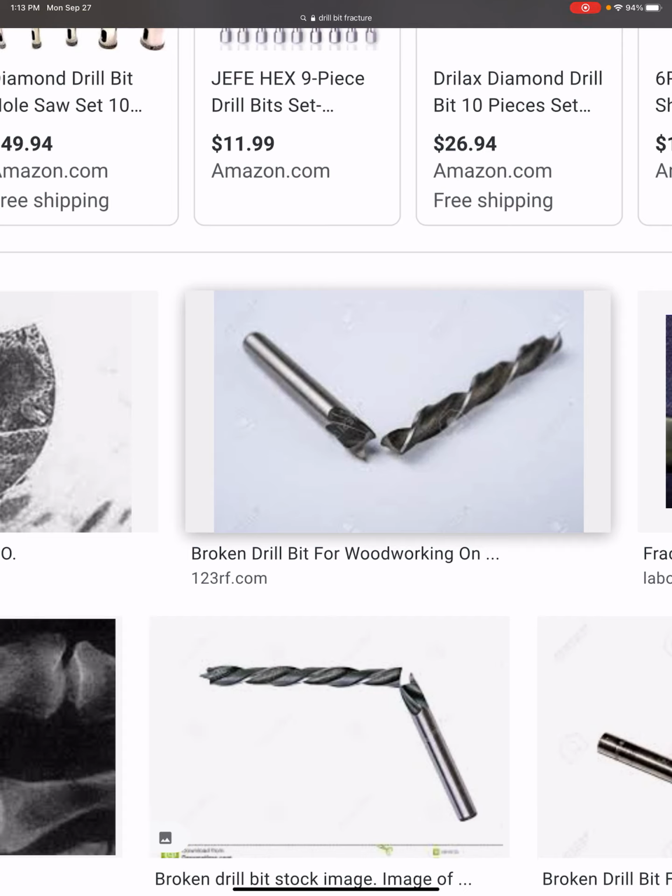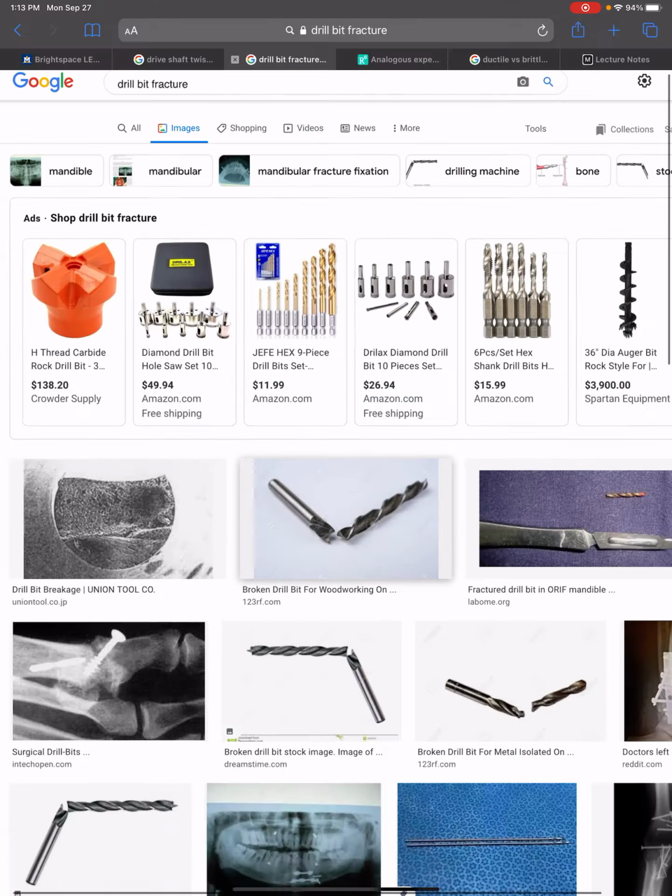And it goes back to, again, those stresses at an angle. That drill bit is imposed with tension forces and compressive forces. Well, because it's a solid piece of material, it can handle the compression, but at a 45-degree angle to that compression force, there's a tension force, and it pops. So it spirally fails around its perimeter.